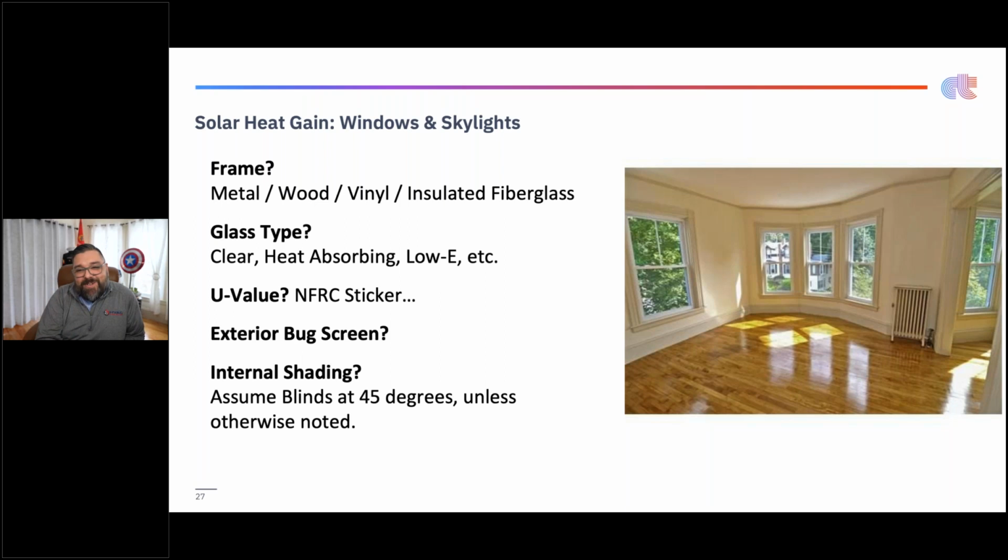The higher the U value, or I'm sorry, the better the U value, the more you're going to end up paying, right? So ideally, we're getting the exact number. If we can't, we're going to start referencing the charts in Manual J. There's a great reference, I think I'll show you next, from BPI, right? So bpi.org has an awesome chart to show you, as you build the assembly, what the U value and the solar heat gain coefficient is for those windows.